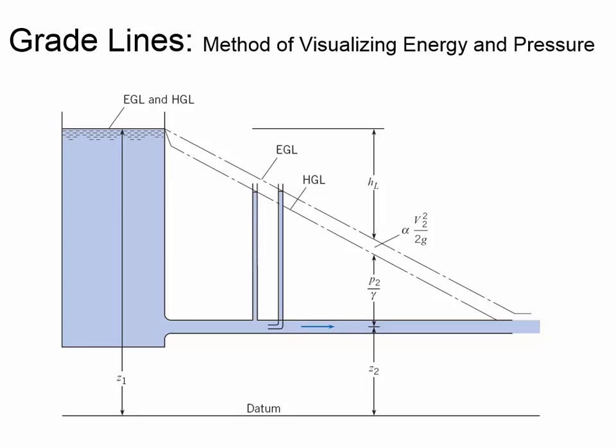And so there is a decrease in pressure as the energy goes from pressure into being velocity head. And so there's an exchange. And that's why suddenly you'll notice the HGL is getting lower than the EGL, because you're losing some pressure so that there can be velocity head inside of the pipe. Any questions from this drawing before we move on to the next sketch?